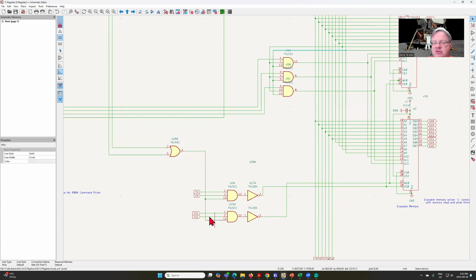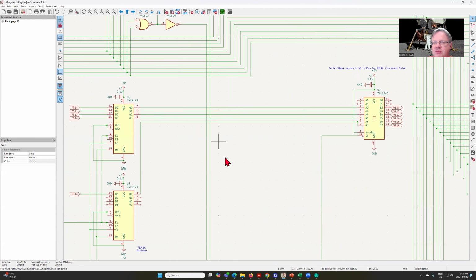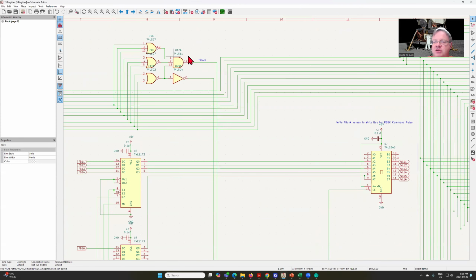Now you notice there's this extra line here, which comes from some logic that we had talked about earlier, which is that there are certain scenarios where we're not really accessing memory, because we have those addressable registers, which are kind of like memory, but not. In those scenarios, we don't actually want to write data into and out of RAM.